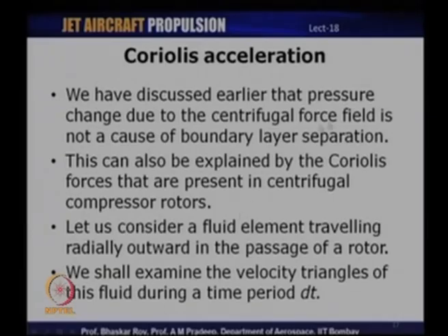So, we can also explain that using the Coriolis forces which are present in centrifugal compressor rotors. Of course, this will also be present in an axial compressor rotor, but we have not taken that into consideration in our design because we were looking at just one radial location of an axial compressor rotor, whereas in a centrifugal compressor the presence of Coriolis acceleration is much more significant.